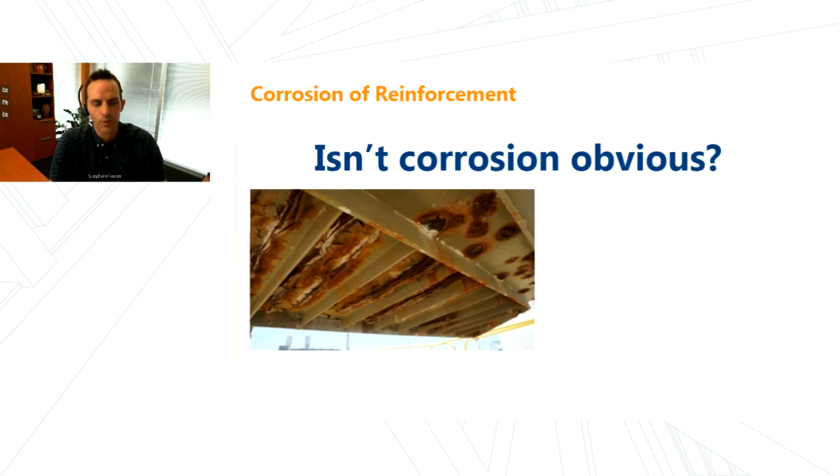And so, when we think about corrosion, oftentimes we wonder, well, isn't corrosion pretty obvious, right? Like certainly for steel structures, here is an example of a steel hatch cover from a plant where, once the coating starts to break down, corrosion initiates, you start seeing the red oxide rust all over the structure. And it's time to do maintenance and recoat, oftentimes in a steel structure.